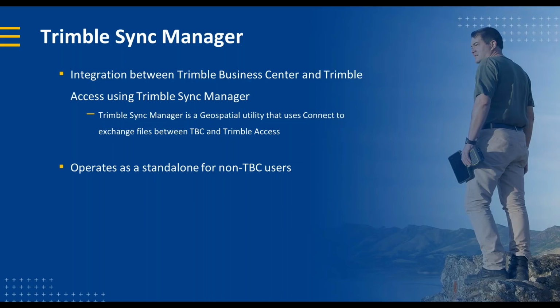Sync Manager. So Sync Manager is a little geospatial utility that we have created that basically users connect in the background to exchange files, but it's sort of an interface between TBC and Trimble Access. So it's getting the data out of TBC into Trimble Sync Manager. You can review it in there, you can add additional things, tweak things, and I'll show you a little bit on that, and then send that data to Trimble Access, do your field work, and then send the data back through Sync Manager. You can create reports in Sync Manager if you want to, or you can export that data back down into TBC. So that's really nice and slick.